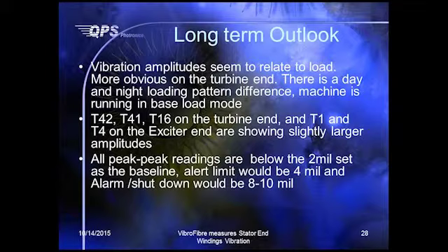The vibration, by the way, can cause actual degradation of the insulation layer. And I'm sure that the problem discovered by the ground fault trip was due to the excessive vibration, which by now is much better.